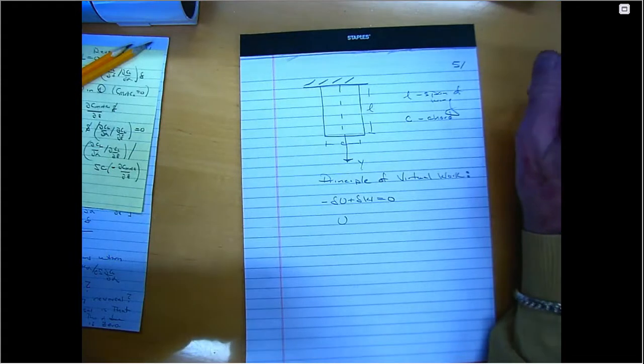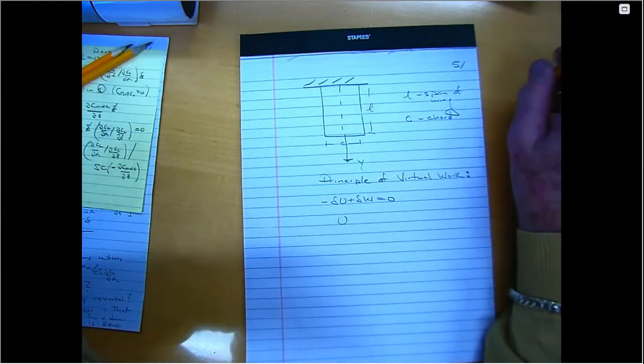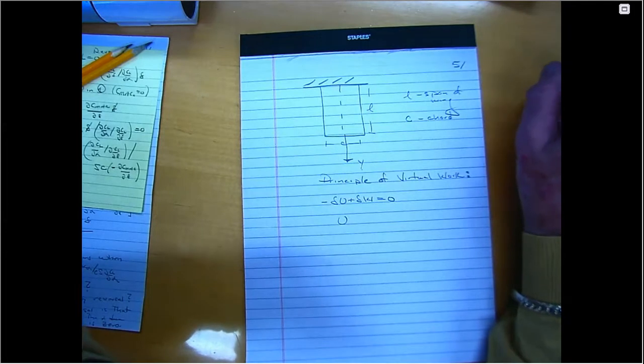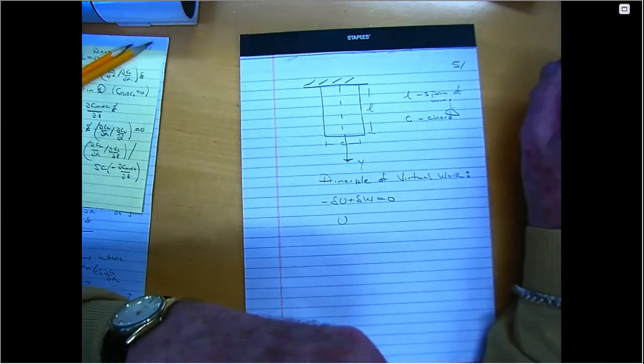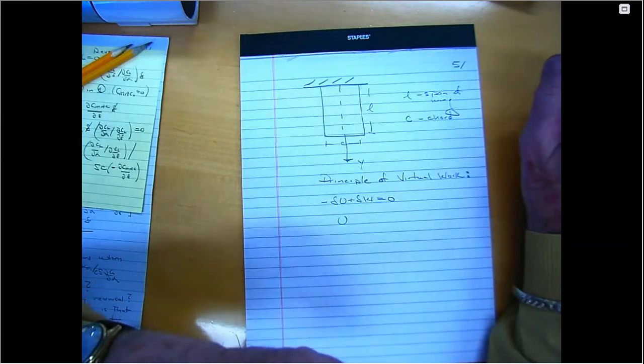I think the question is, when is the lift 0? And the answer is the lift is not usually 0, but there is a certain value of dynamic pressure at which it is 0, and that dynamic pressure is the reversal dynamic pressure. A few moments ago, we tried to calculate that.